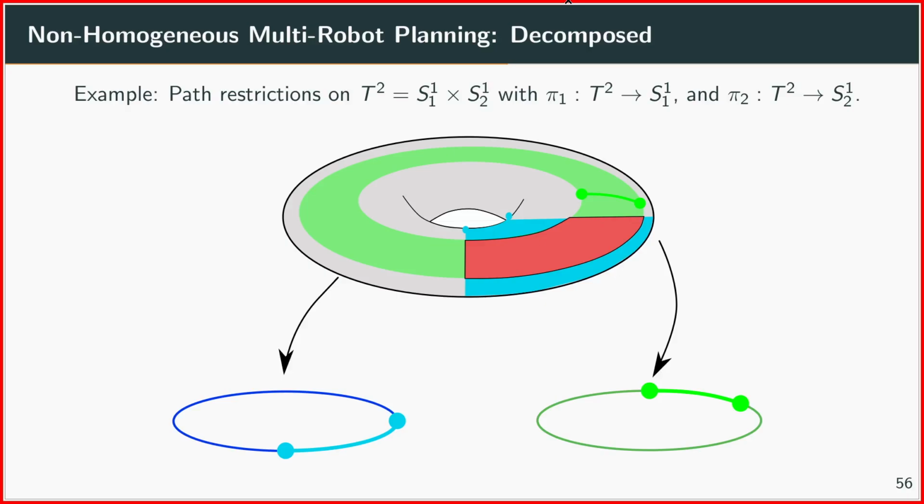And then what you need to do is take the intersection of those path restrictions, and you can now do motion planning in here, which basically means that you move the robots only on this path here. You can move backwards or forwards, and you try to find an optimal solution by just staying on those paths here. And that basically gives you, for example, if you would use RRT, you could compute an RRT solution for this problem.